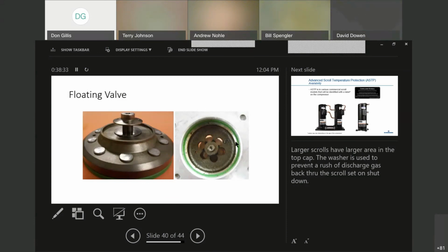Okay, so keeps it as efficient as possible. Remember, re-expansion gas is a bad thing. It's gas that we've already pressurized. We paid to do that already, and we're actually pumping it over again. So you'll see these check valves stopping any gas coming back in.